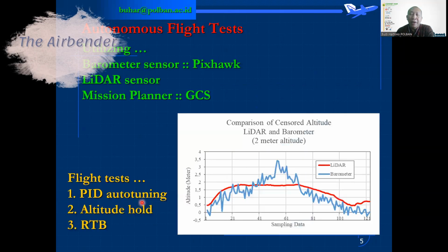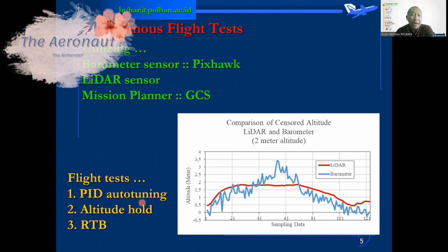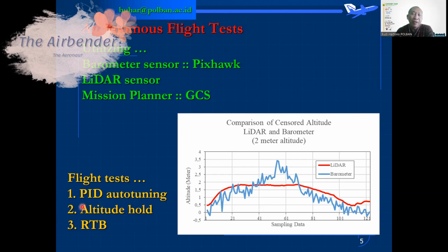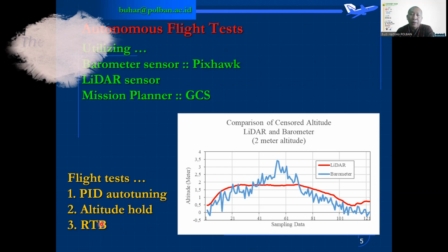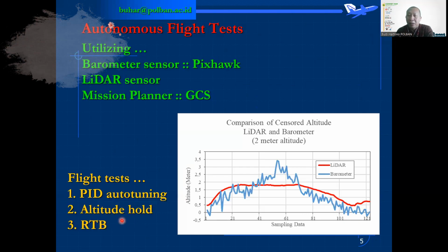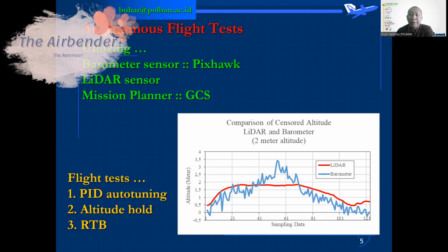In this research, a series of flight tests were carried out. First, the PID auto-tune flight test to obtain proportional, integral, and derivative constants that we'll use in the autonomous flight. Second, the altitude hold flight test to ensure the quadcopter flew at a fixed height from the ground.